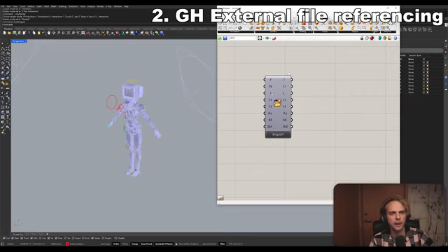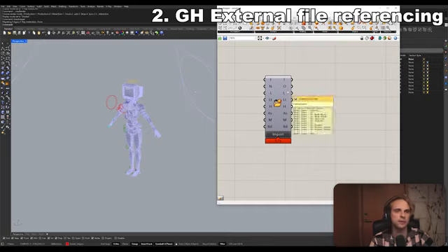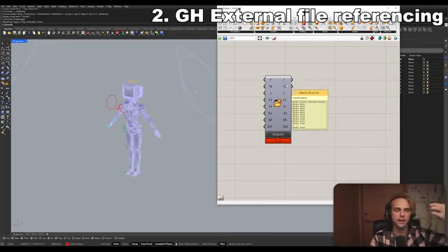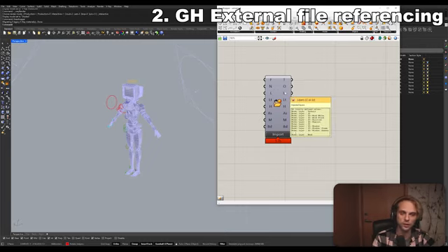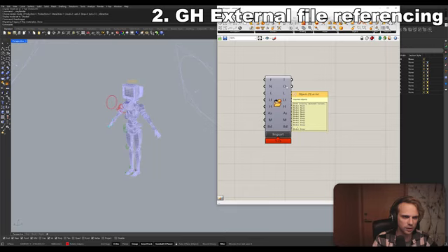All right. And all I need to do is just hit import. Give it a second. It imported, and now the outputs are basically all of the model transforms of the current model, all of the objects, all of the layers that are being used. The objects don't come in just as a mesh or a B-rep, they also come in with layers associated with them in their metadata.